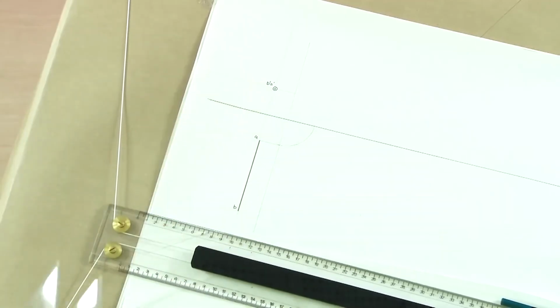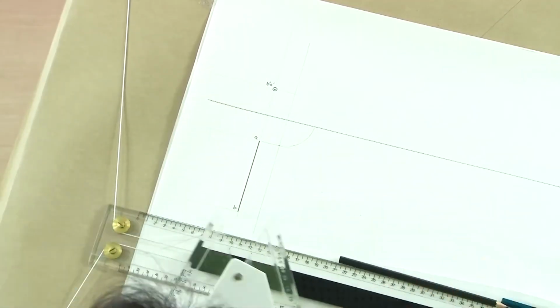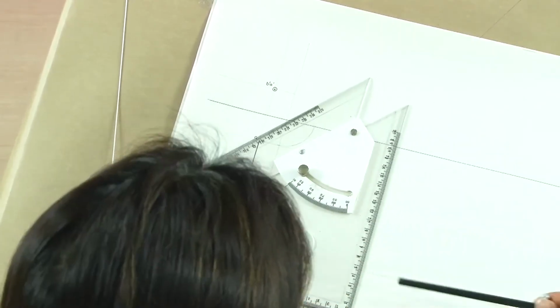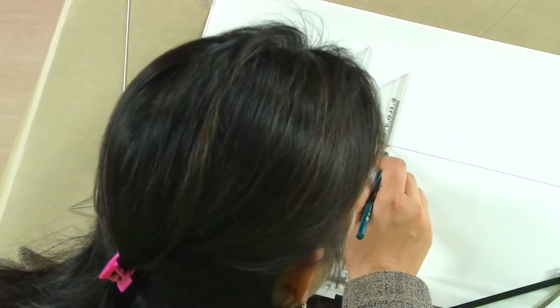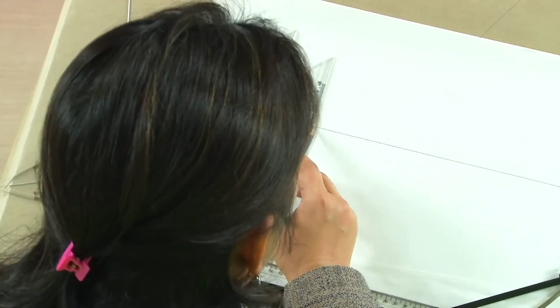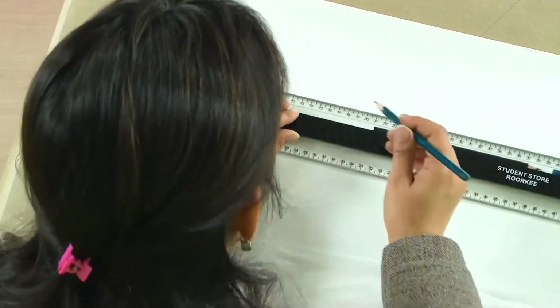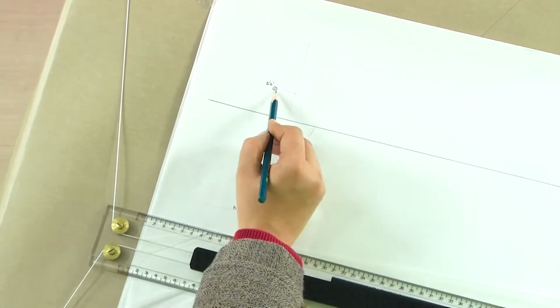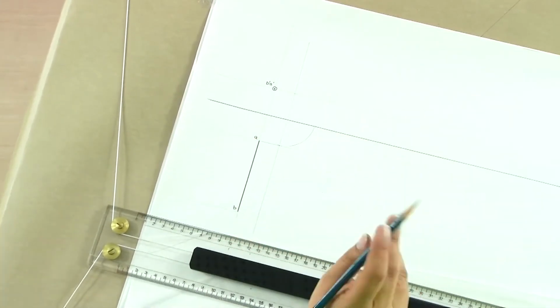Now, take the projections and you will know how to mark or visualize the line in side elevation. So, we first take the projections horizontally, because these are orthographic projections, so all the lines will either remain parallel or perpendicular to each other. And here we draw another projection line coming from the elevation. Now, match the point.